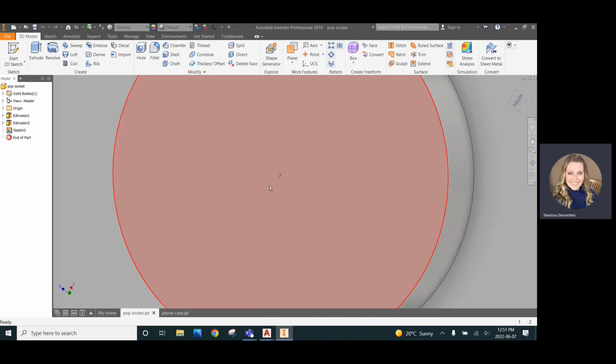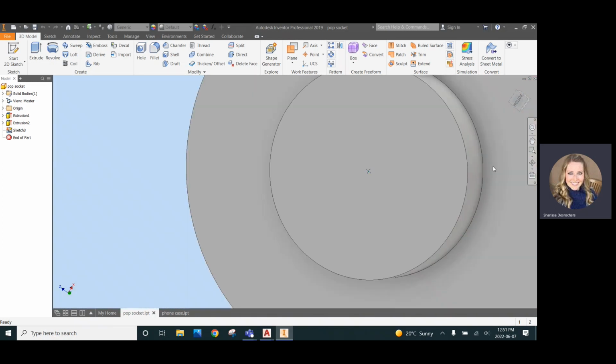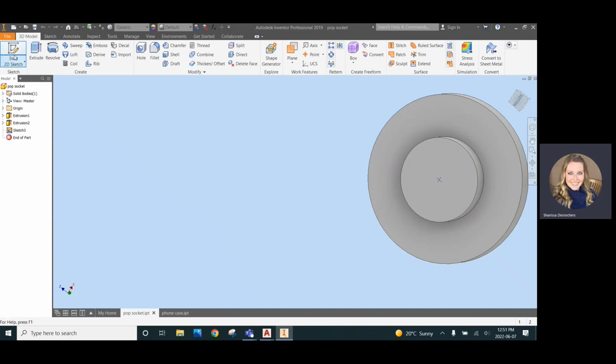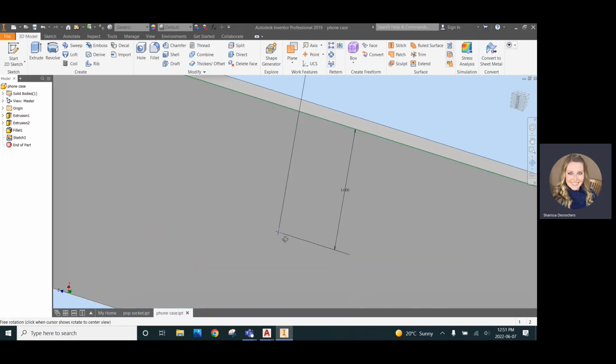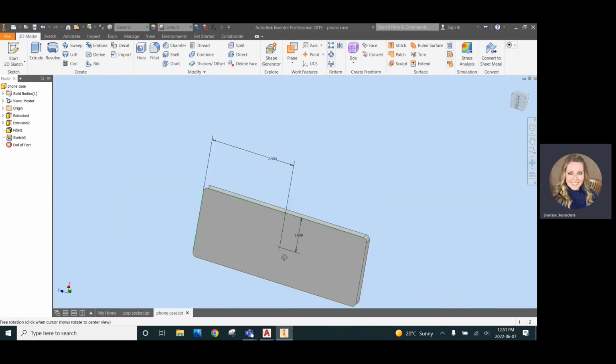I don't know if you remember when we work in Inventor, before you make a hole, you can use that command in the drawing bar called point, center point. I put a point right here, and then on my case, on the back of it, I put a point. The reason I did this is it makes it so much easier when you go to try to put 2 things together if you have a location of where you want the 2 things to mate.